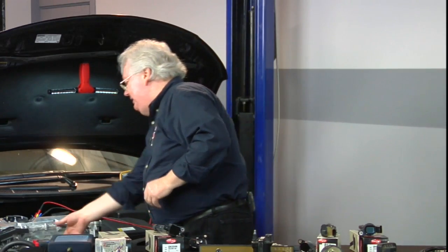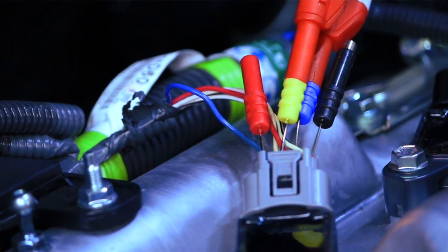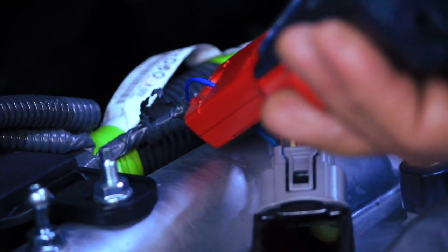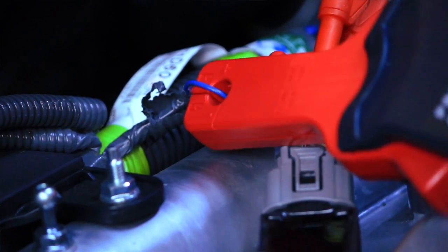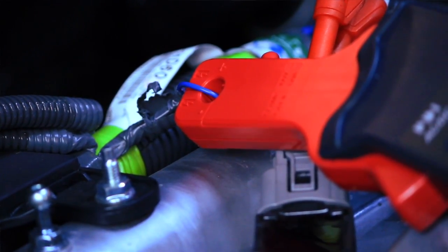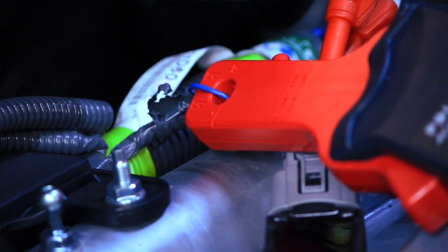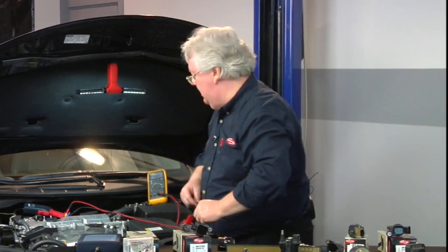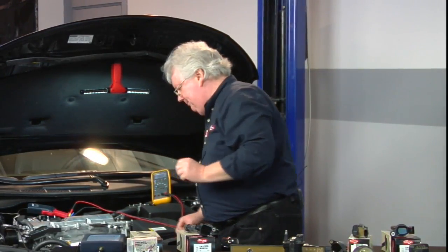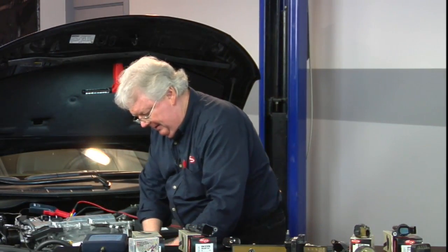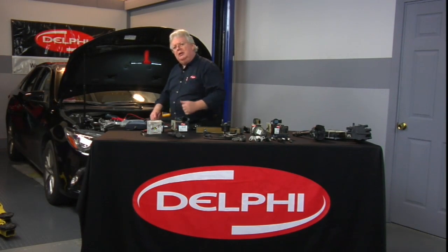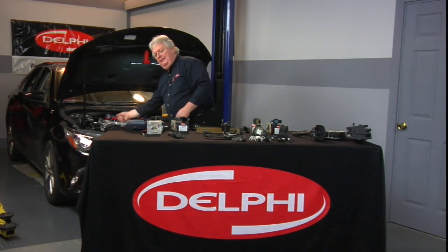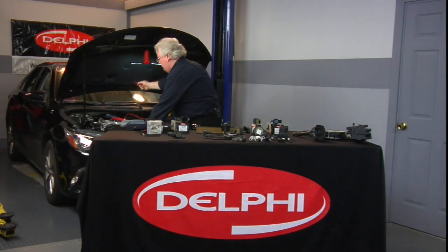So what I'm going to do, I'm going to take an amp clamp. It's going to be in channel 3 of my 4-channel scope. There we are. And it's going to go around the ignition feed wire, which is this blue wire I probed with the red. So I just have an inductive amp clamp, but instead of hooking into the meter, it's going to be hooked into the scope. All right. Now we're going to take channel A. That's going to be my trigger from the PCM, what I was measuring a minute ago with the Fluke meter in frequency mode on voltage, frequency.